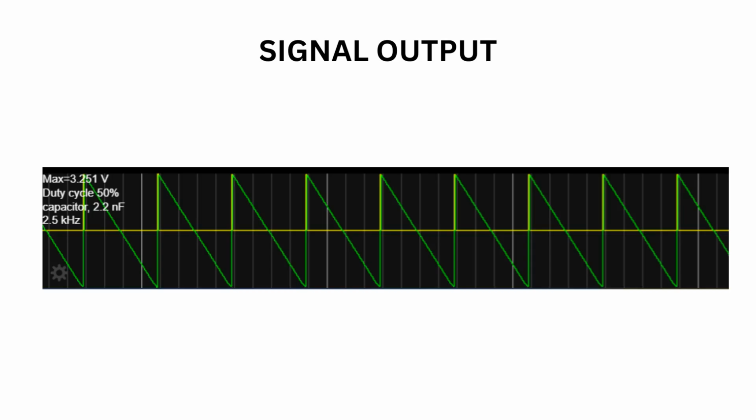This measured waveform closely matches both the ideal piecewise model and the Fourier series reconstruction, confirming that the mathematical analysis accurately predicts the behavior of the physical circuit. This completes the link between theory, simulation, and practical signal generation.